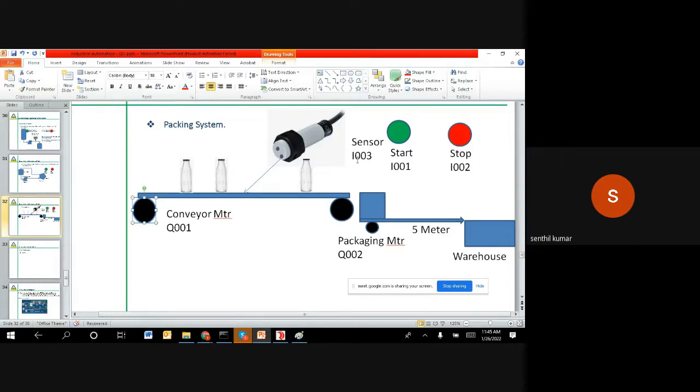But in case you want to abort the whole production, if you push the stop, everything stops. That means no more movement, nothing can go. The continuous chain we talked about will break. It's a little tricky logic, but if you can implement it, that shows you have a better understanding, because looping is critical.